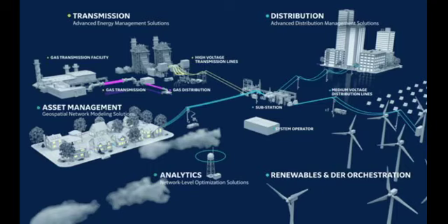Power oscillation damping. FACTS controllers, particularly thyristor-controlled series capacitors, TCSCs, and thyristor-controlled braking resistors, TCBRs, can dampen power oscillations caused by various factors such as generator imbalances or sudden load changes. This improves the stability and transient response of the power grid.